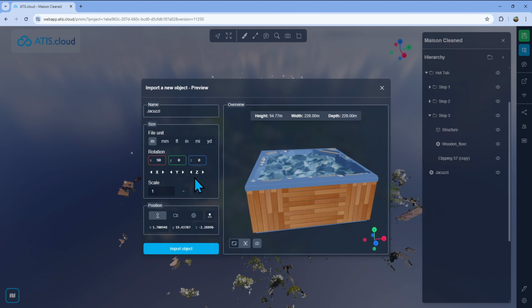Then what I did was create the entrance. So now that we have our two boxes, exterior and interior, we basically have the overall shape for our garage. But now we'll actually need to be able to get inside of it. So what I did is create another clipping box called garage door, and that would cut open the front of the garage, okay? But now you can see, obviously we're going to be seeing some gaps here, down there, here on the right and everything, because the gap between the exterior and the interior is not filled. Okay, these are just two simple boxes, but the gap that we have between those two is not filled.